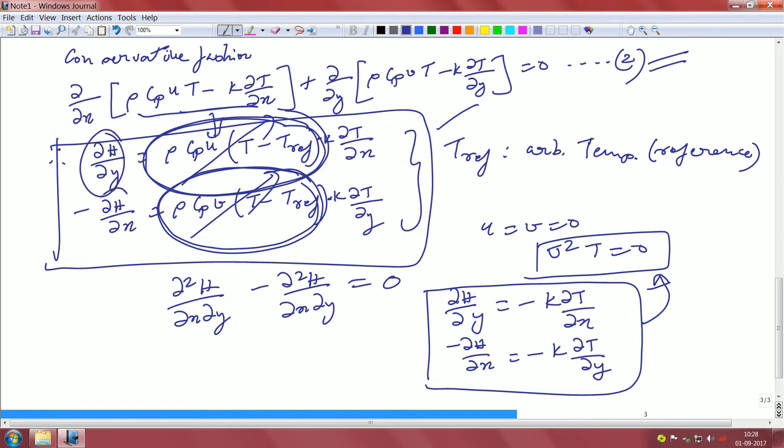So, if you plot this h now in a flow field, you should be able to describe the heat flux or the heat lines, or the flow of heat rather, quite imaginatively, because it is exactly like the stream function, with all the problems that the stream functions also have, got it. So, this is a useful way of starting, though it is not frequently used in the literature, because we still use the temperature field even now. But in some cases if you want to know the flow of energy, then this particular concept becomes very useful.